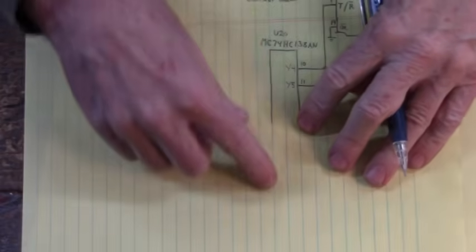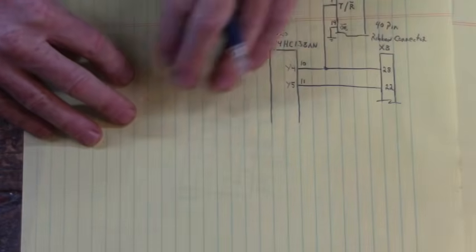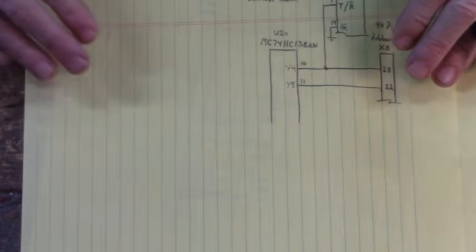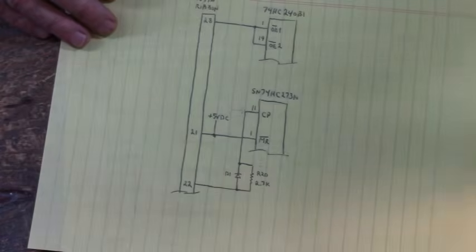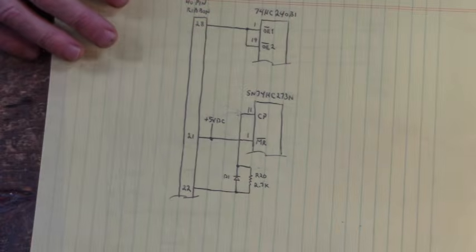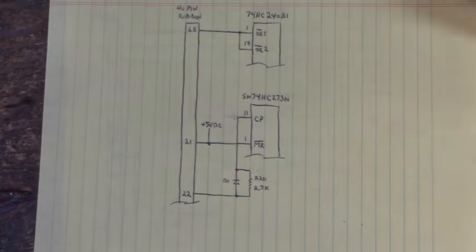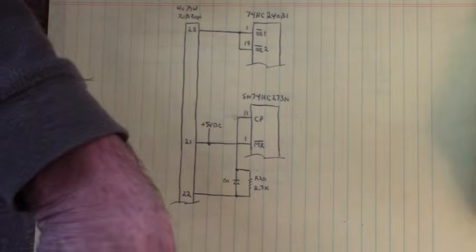I should have, but it's going to run back to the processor to address your clock and output enable for that 74HC240 and the 74HC273. That's all going to go back, be controlled by the addressing of the processor. I might follow that out if I ever have to, but let me show you where all these things are.